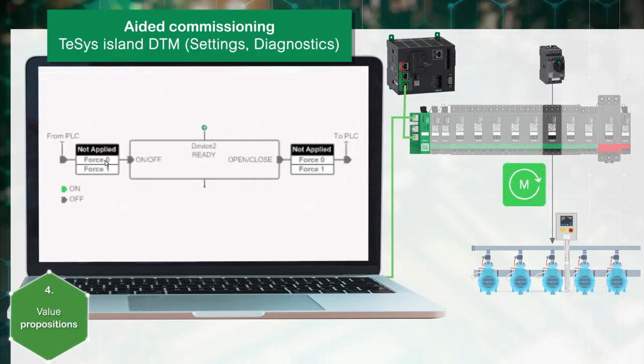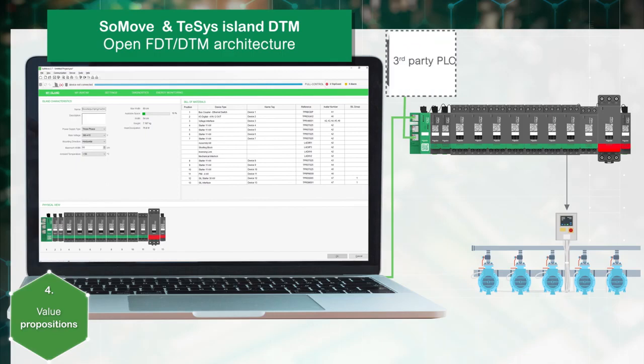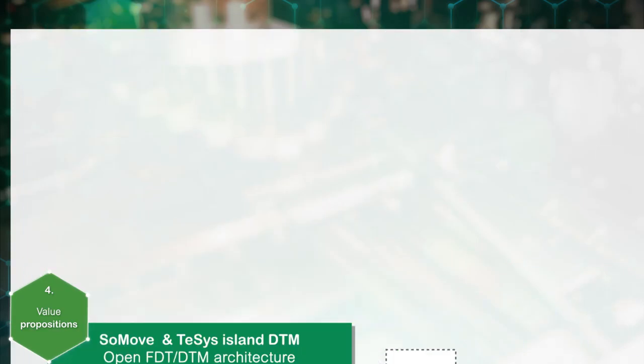For enhanced diagnostics, the force mode allows you to simulate PLC inputs and outputs. The test mode allows you to check electrical wiring and devices. Thanks to the open FDT DTM architecture, SoMove is the engineering software in a third-party automation environment.